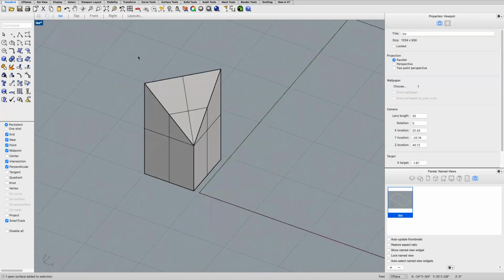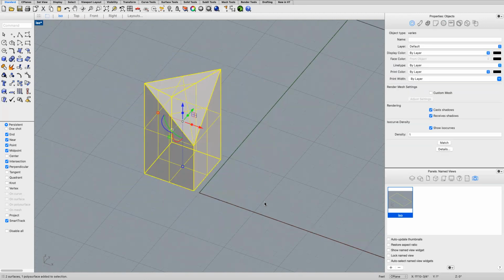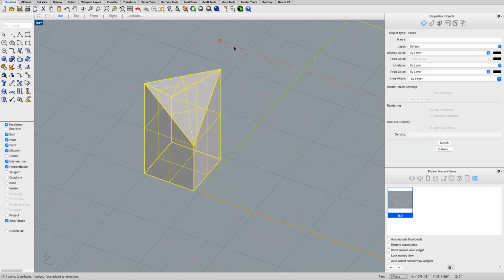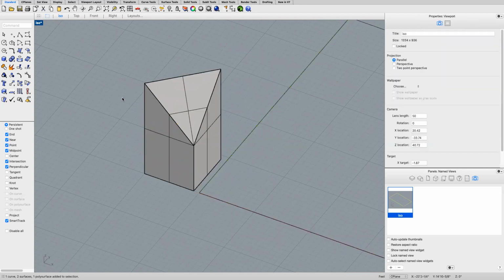Now, you probably know this, but for selecting objects, it matters whether you drag right or you drag left. Right is a solid line, so there's a solid line around that box. This selects everything that is within the window, versus when I drag left, it's a dashed line in that box, and that selects everything that's touching the window. So that's a way that you can often select from a group.